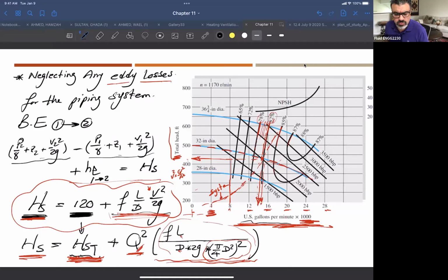One thing that we mentioned also for this type of pump is that, because of the design of the pump, you might have some variable flow rate at the exit. But with a certain design, for example a gear pump, this fluctuation becomes very minimal, right? Every time we run this pump at a certain RPM, we are 100% sure that the flow rate coming out of this pump is that much, because the pump doesn't depend on the pressure. If you have any restriction in the system, the pump has to push the same fluid, right?